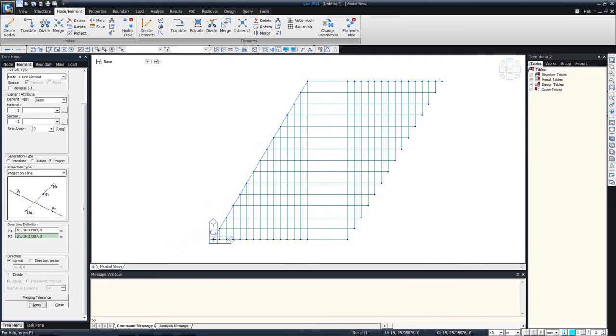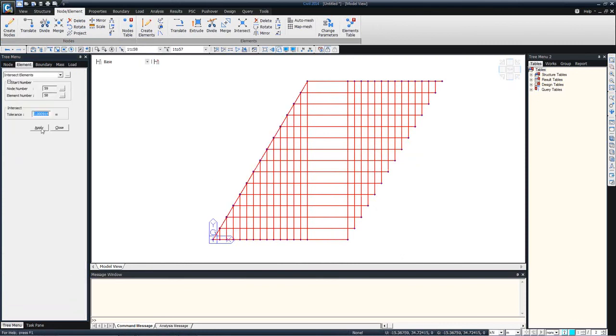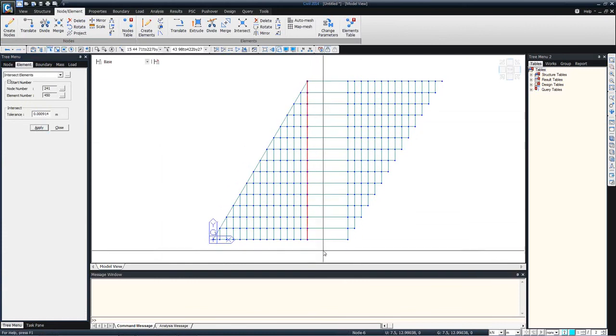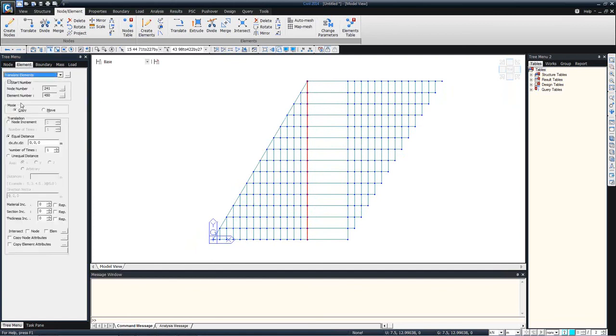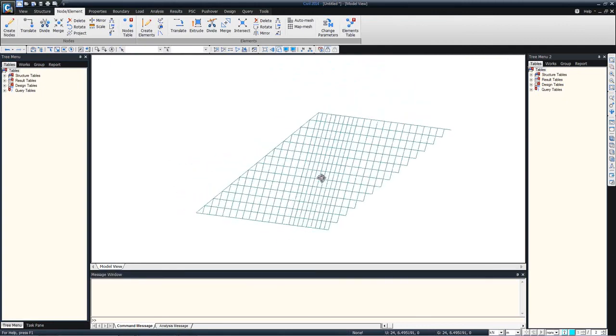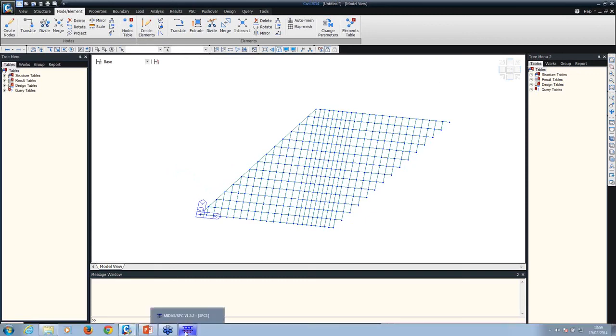Now for in between, we need to make sure that they are intersected properly, so I'll select everything, elements and intersect. So they are intersected, and just to fill up in between, go to translate elements and just measure the distance, 9, 8 times, apply. So that's your transverse grillage modeled, and you can start assigning properties or sections to different parts. So that's how quickly you can generate the orthogonal grillage.